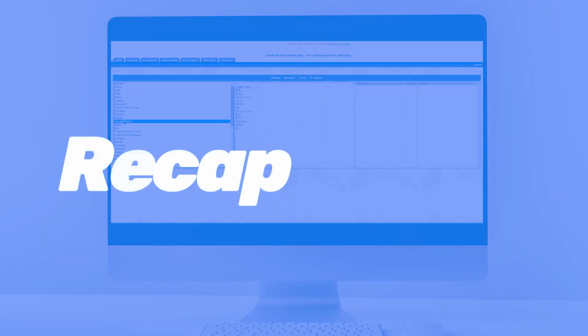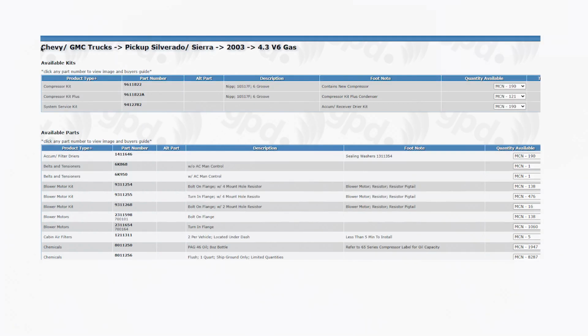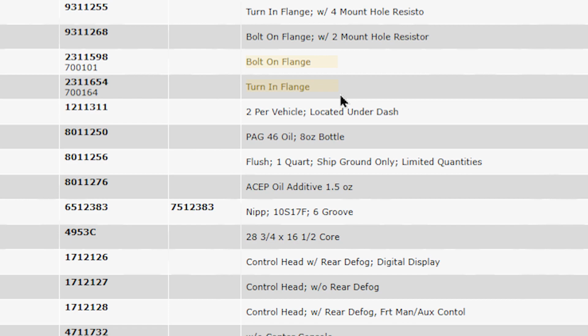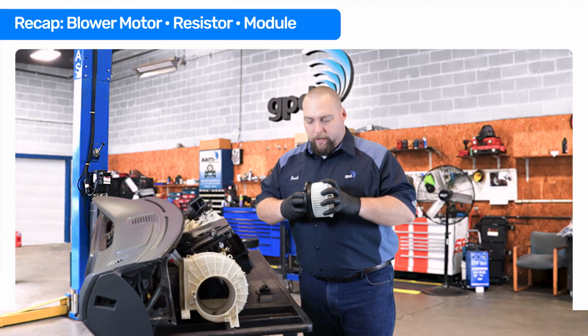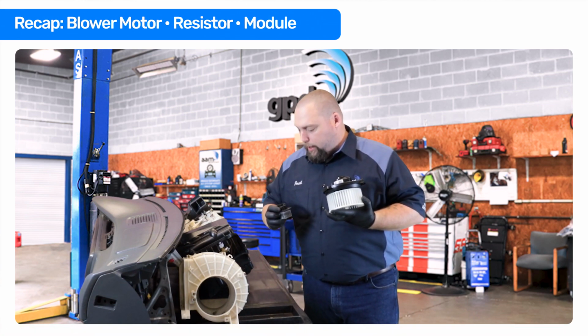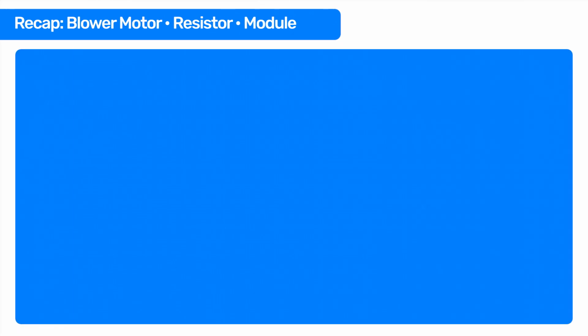So for counterpersons, when you're looking up your blower motor for your vehicle, just make sure after your make and model, make sure you're getting the front or the rear blower motor. Sometimes you have a turn-in flange or a bolt-in flange or a different electrical connector on the blower motor. If there's any burnt spots, anything like that, you want to go ahead and recommend a blower module or blower resistor, as well as the wiring, the pigtail for the system.